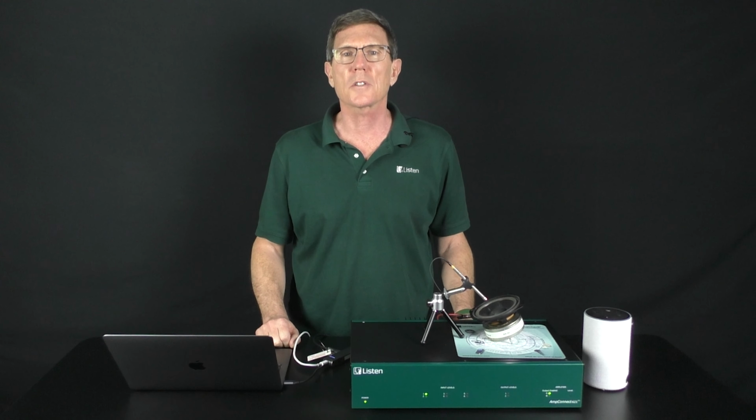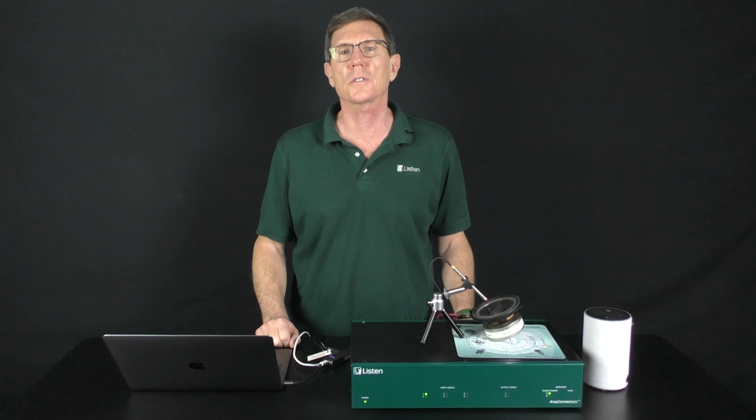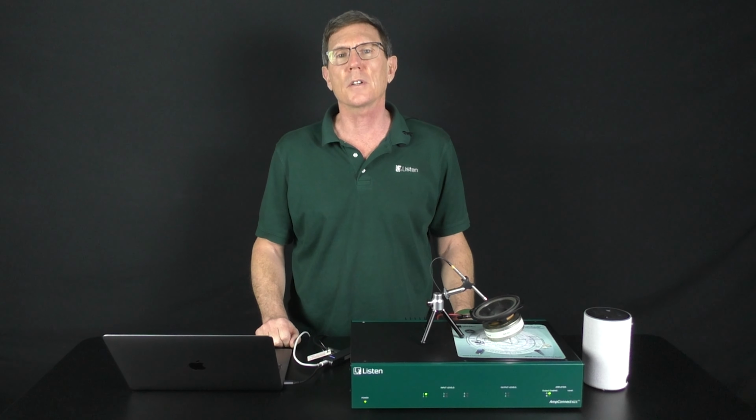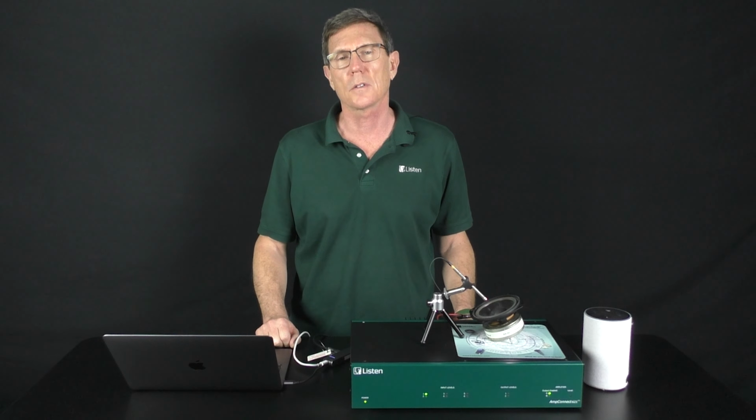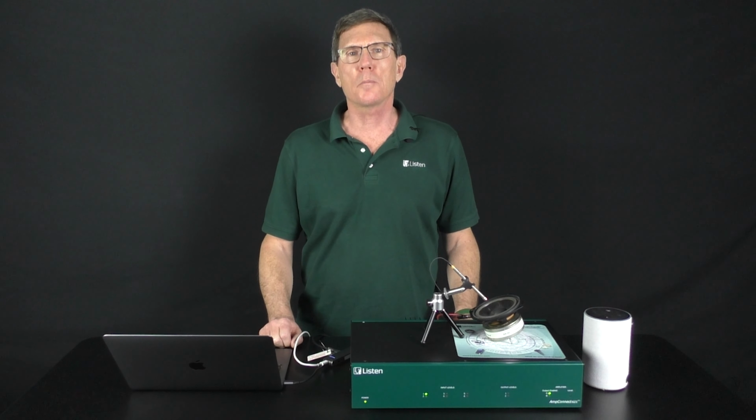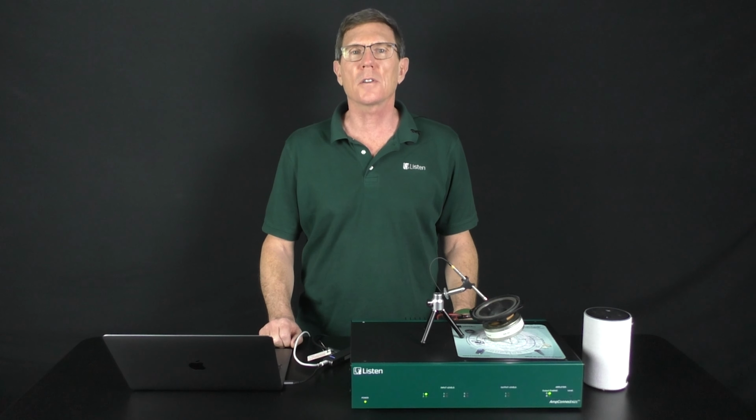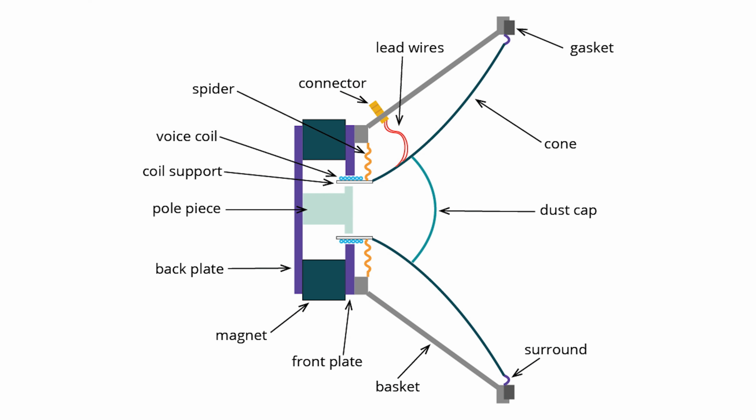This single distortion metric can be useful for production line pass-fail testing, but it does not reveal the precise failure mode and is susceptible to background noise, which also has a high crest factor. This is important as transient and periodic distortion are caused by very different mechanisms. In a speaker driver, periodic distortion, often known as rub and buzz, is caused by a rubbing component. For example, an improperly centered voice coil or poorly glued components, such as the surround or spider.